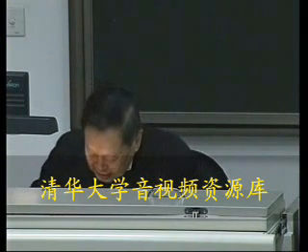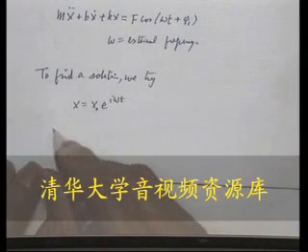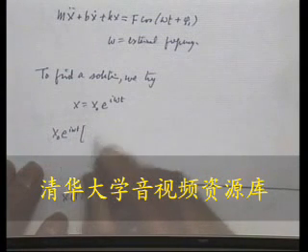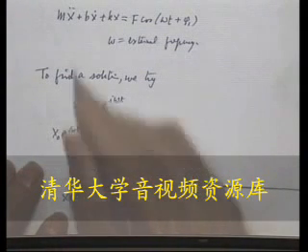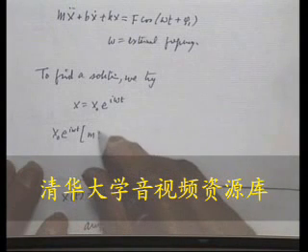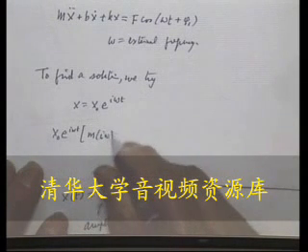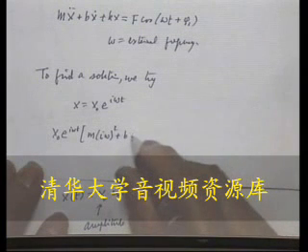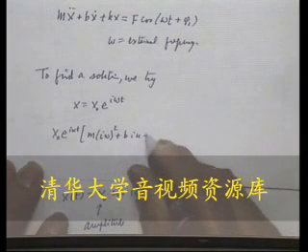So we put that in there. Then we get x0 exponential i omega t times m times x double dot, which gives minus omega squared, plus b x dot, so I get i omega, plus k.